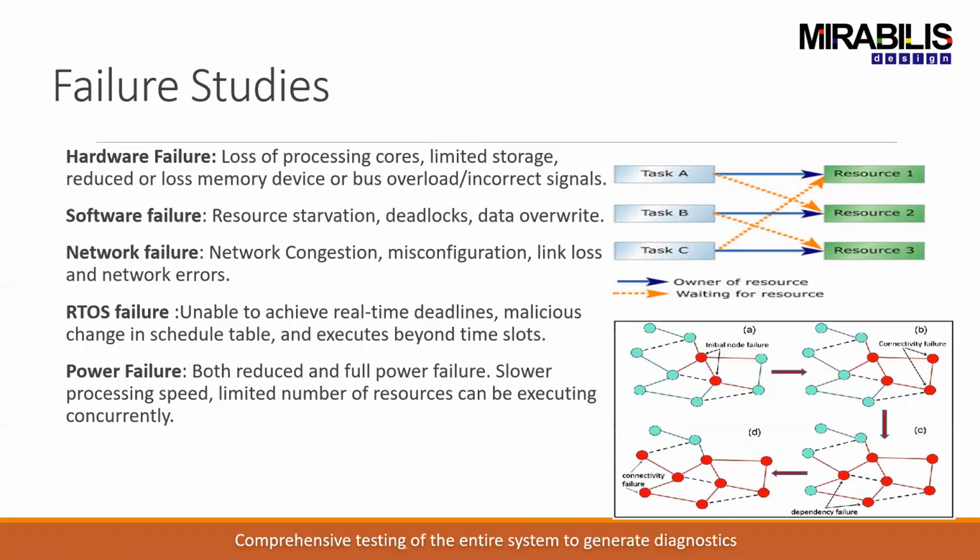So for example, you saw the thing where the road condition sensor sent data where it was processing it incorrectly. So you want to be able to capture those. Those are part of my failure study. Like what happens if one of the codes fail? Or for example, in my software task diagram, I have it where I need these semaphores, but to release the semaphores, I need this one to complete. So I've got kind of a deadlock. Being able to evaluate all of that at the system level is kind of critical.